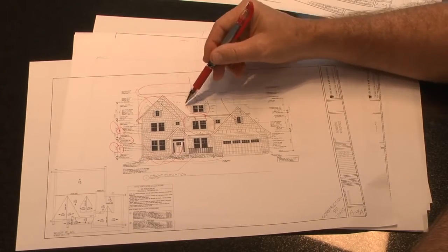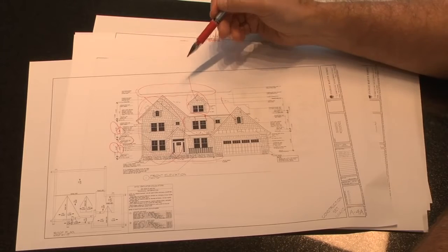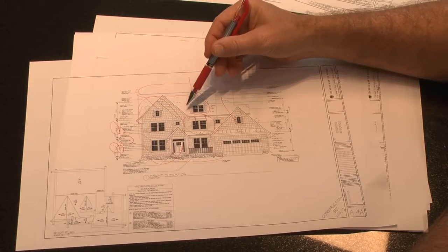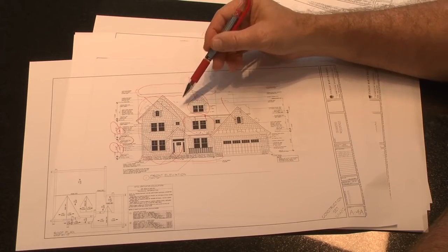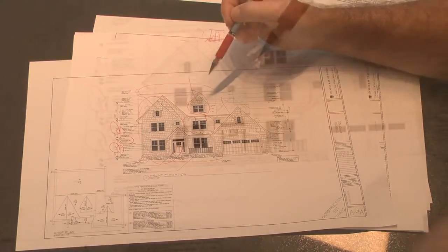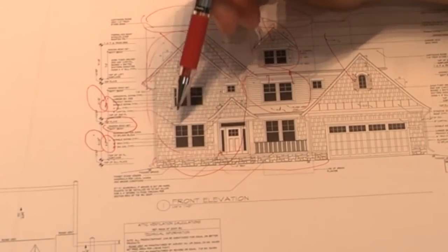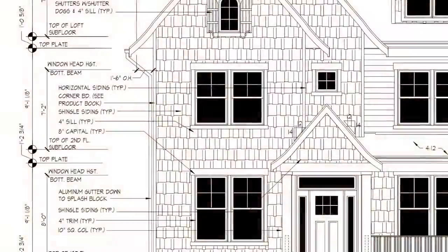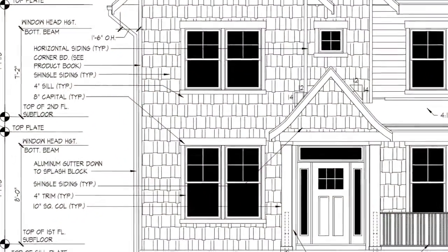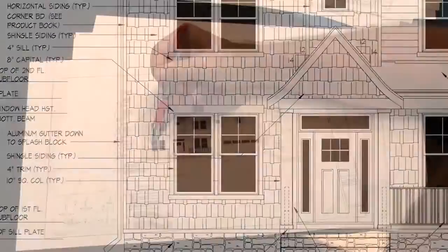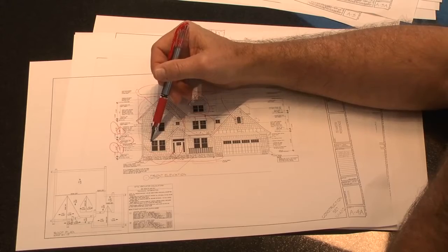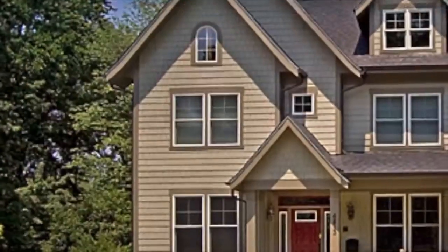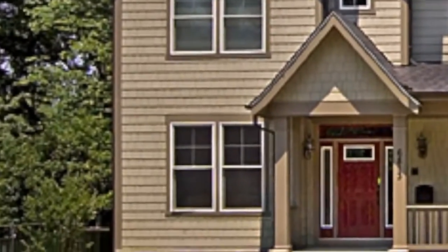This is also what we call a faux dormer. Again, it's a real dormer. They're real windows, but it's leading to nowhere. So this is purely for exterior presentation purposes. A couple other things to go over with you is on the front of our homes, typically we'll do a taller head feature over the windows. So typically we'll do 4-inch vertical legs around the windows with either a 6 or 8-inch head feature, and that's just really to make the windows pop.